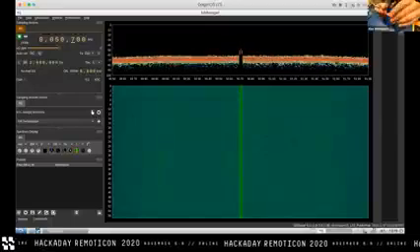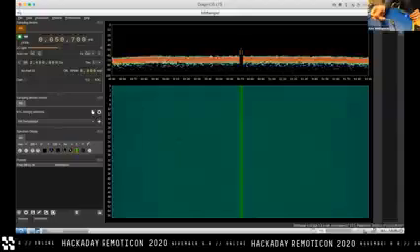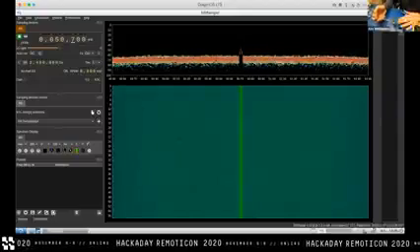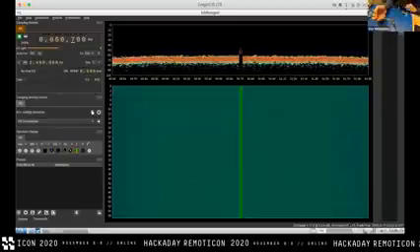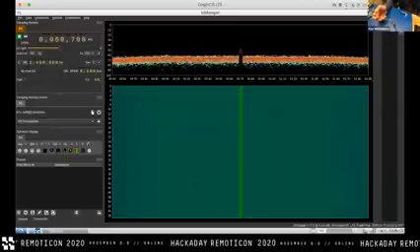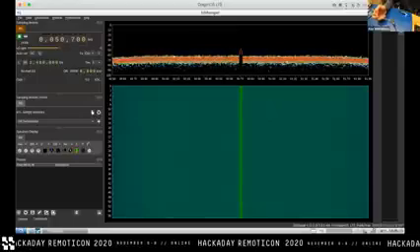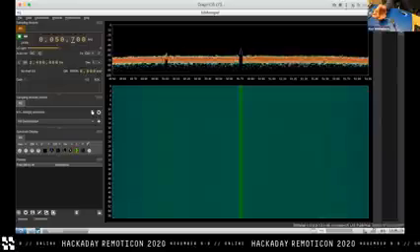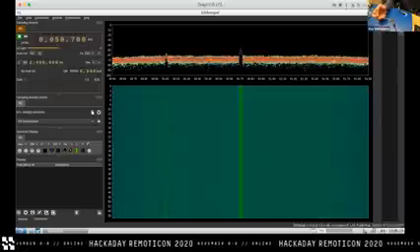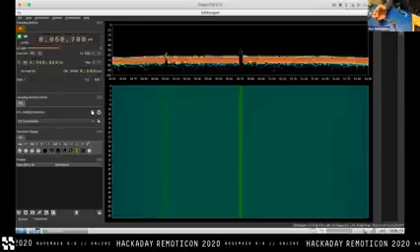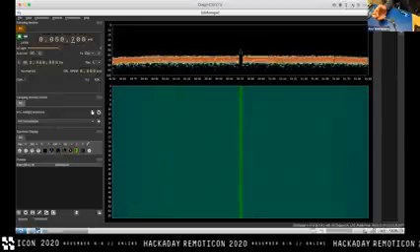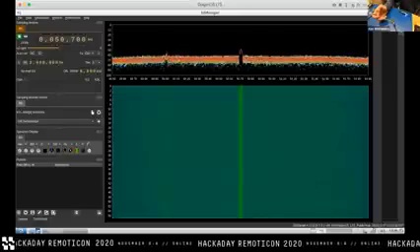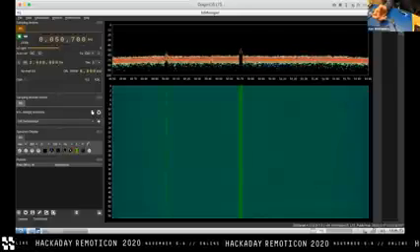If I switch over to this other probe, okay. I'm going to use the probe. This is the plane of the opening. I'm going to wave it around above my board the same way I just did with that other probe. There's basically nothing to be seen because this probe is really not sensitive. Turns out we're emanating the signal in a very specific spatial region. And this is why you start with the bigger probes, because it'll pick up much more and give you an area to narrow in on.